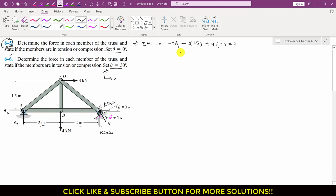So when we solve this, AY will be equal to 3 into 1.5 minus 4 into 2 divided by minus 4. So from this, AY equals to 0.875 kilonewton, right? So this is AY.